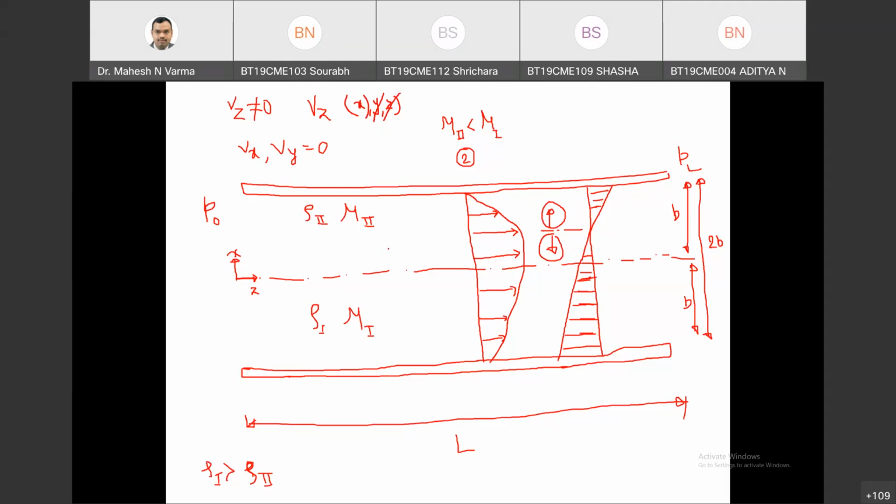No, the reason is that at the wall there is a velocity of 0 and there is some velocity at the intermediate point when I am moving in X direction. Yes, sir, the velocity at the wall is 0 because of the viscous forces, right? That is called the no slip condition.